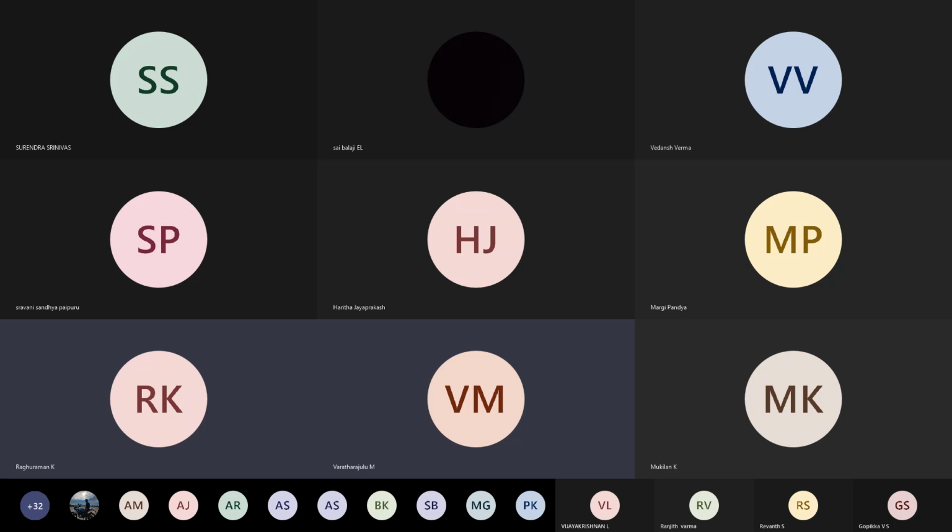These ladles are mostly specific for large moldings, and their size is designated by their metal holding capacity. Then crucibles. Crucibles are made up of refractory materials, similar to ladles, and are used as melting metal pots for small scale moldings. That's it, sir. 14 things over.